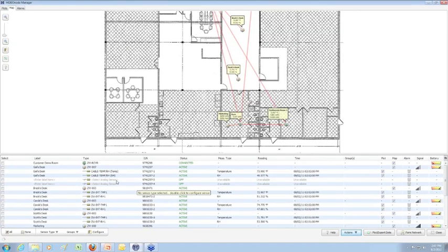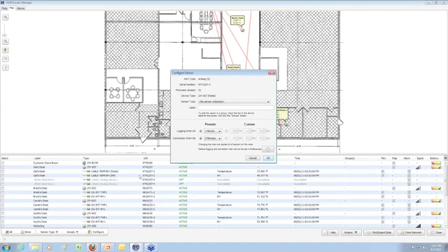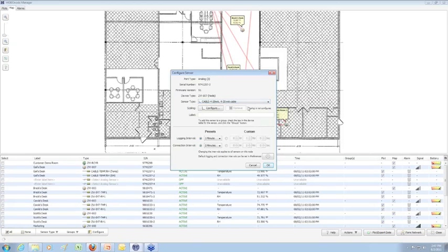We do have another question in terms of if you're using an air velocity sensor, how do you set this to get it to CFM? Anytime that you have a sensor that gives an output of, let's say, 4 to 20 milliamps, and it's a sensor that we don't offer directly, you use one of our input cables. So let's say, for example, it did have a 4 to 20 milliamp output.